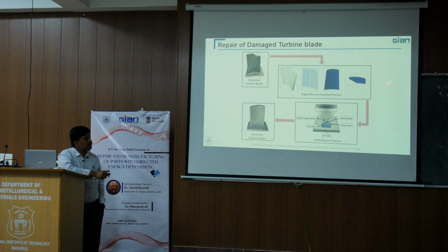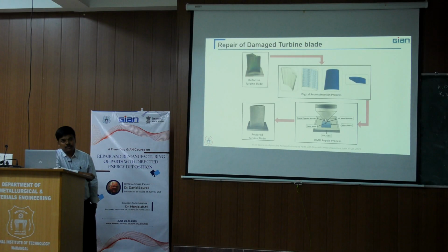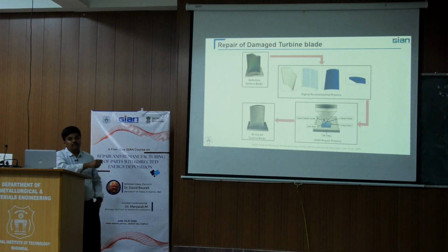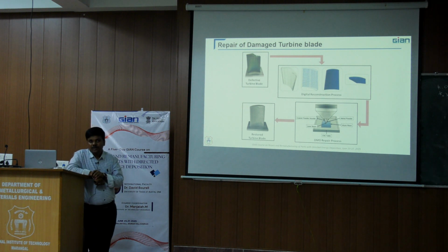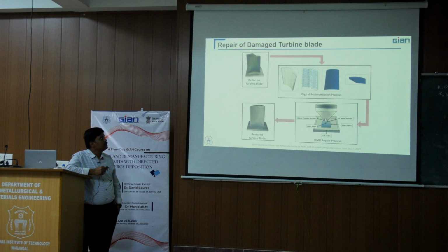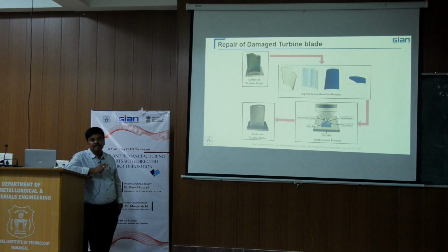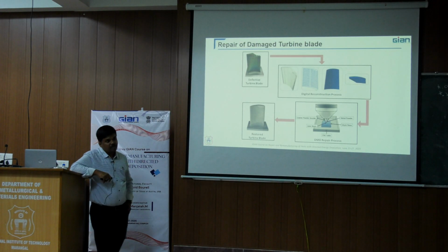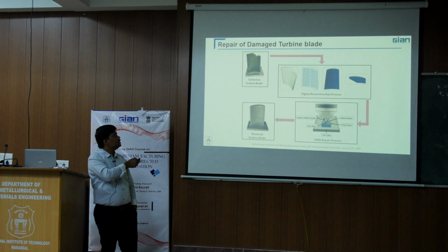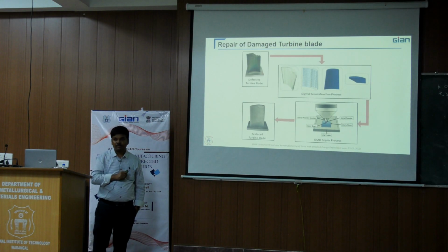Then for only that much of the part, we have tried to develop scan strategies or deposition strategies. But for the existing direct part, we cannot repair it, because we need to provide some machining, the milling we have done, to make it easy so we can deposit the additional material. Because if you see, the surface is not completely regular.